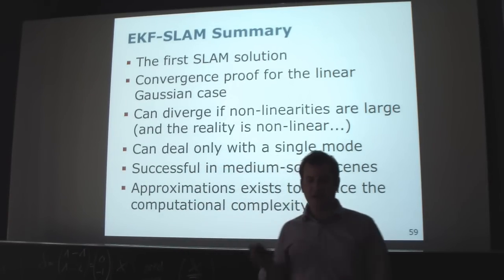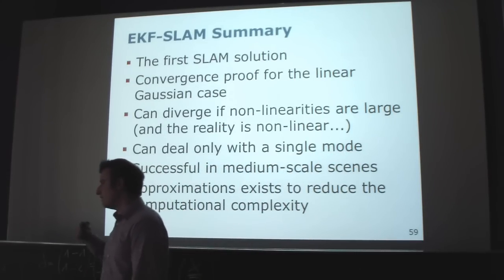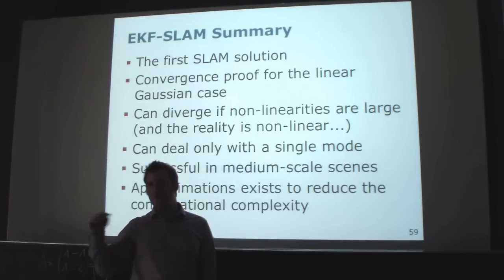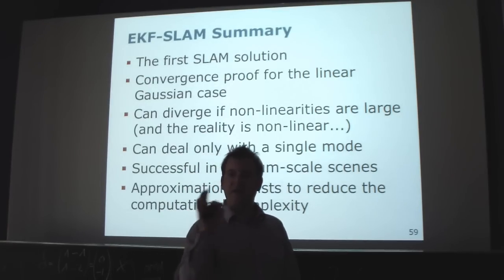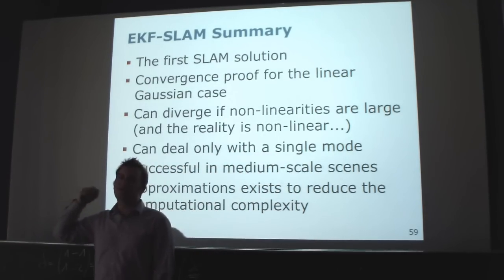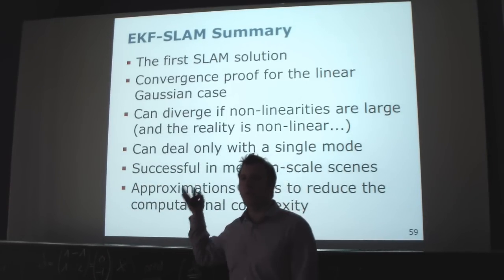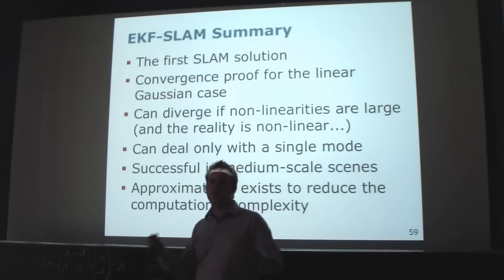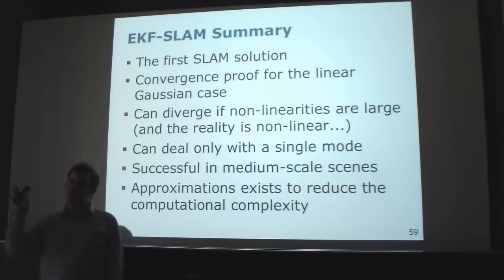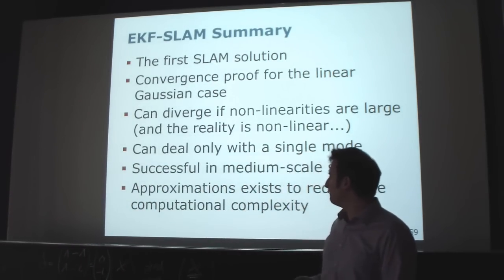So far it has been applied to kind of medium-scale size. Also, if you have the possibility to perfectly engineer your environment, let's say you can place perfectly distinguishable features in the environment for an industrial application, it can be a good choice to run that Kalman filter, because if you can engineer an environment, you can make sure that there's no ambiguity in the data association. Why not use it? And if the environment is not too huge, it's a well understood technique. It's been investigated since the beginning of the 90s, and successful systems have been around in the 80s.